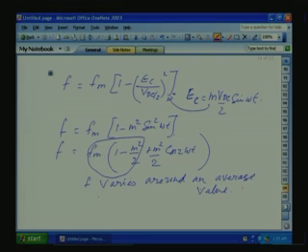So, let us find out what this average value is, and it depends on the modulation index. So, for variable speed operation, we have to design the hysteresis band either for the maximum switching frequency or the average switching frequency, you can decide. Let us see how this switching frequency variation is varying at 2 times the frequency with respect to the back EMF. Let us study in the next class.